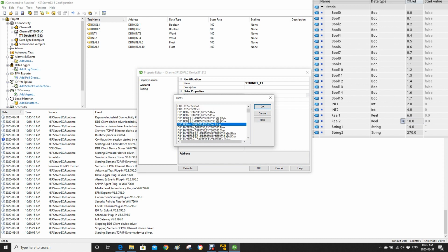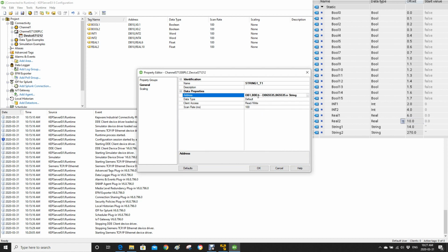The first way, let's hit this, string byte, which means the byte B here, that is the start byte, the string start. And this N means the length of that string. So it has a tricky part here. Let me select this first. I will explain after. It starts from our DB, that is 10, and the byte, the first string from this list, starts from byte 14, okay? And the length, by default, I will show, let's say, 8 characters.